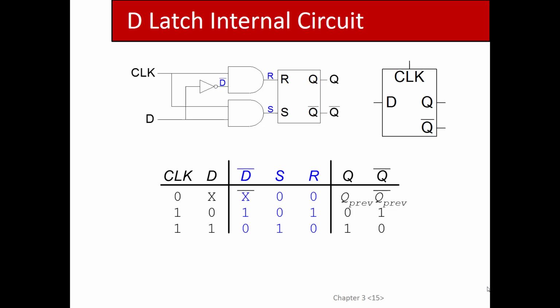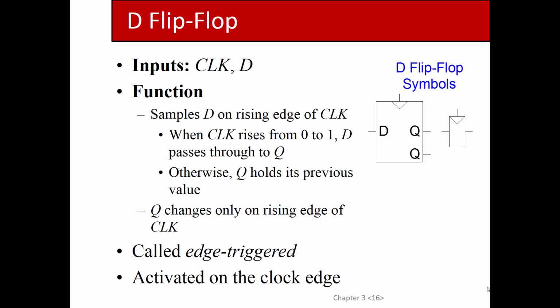Latches are difficult to design with. Instead, people use D flip-flops. D flip-flops are much more common than latches. D flip-flops are very similar to latches, but they have one difference: instead of capturing Q when the clock is high, it captures Q on the rising edge of clock, or you can also alternatively make it the falling edge of clock. But the point is that instead of capturing Q whenever clock is high,